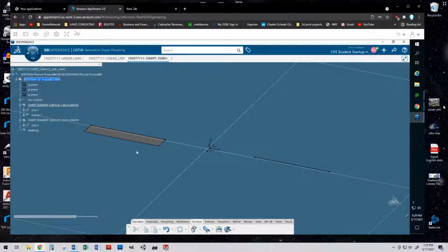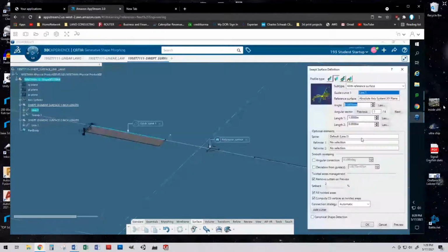Just for kicks, let's reverse the direction. So how would I reverse the direction if I wanted to? Well, we can pick a different angular center, or we can key in like 2 instead of like 1. No, probably the easier thing to do is, no, choose. I want to go the other direction, not change the length. Yeah, you want to move in a negative x direction. I just want to click that arrow so it's going in the other direction.